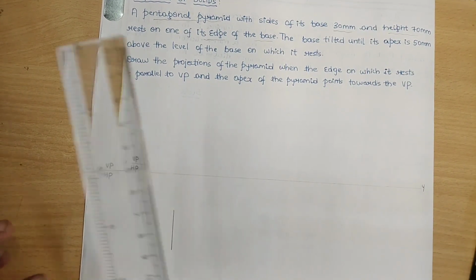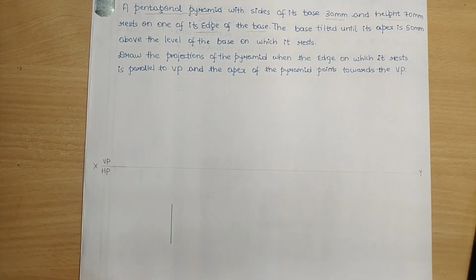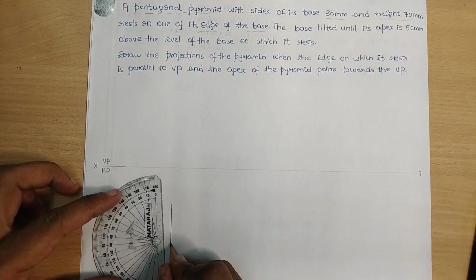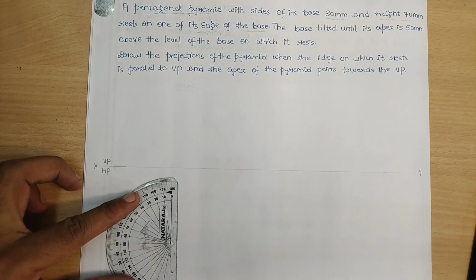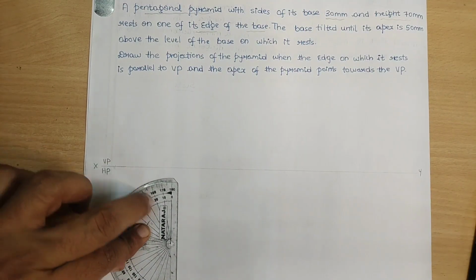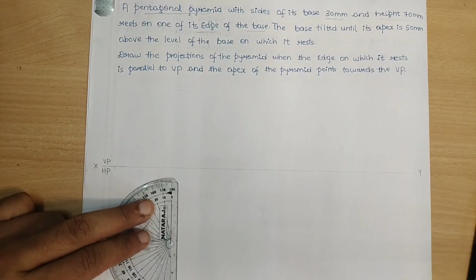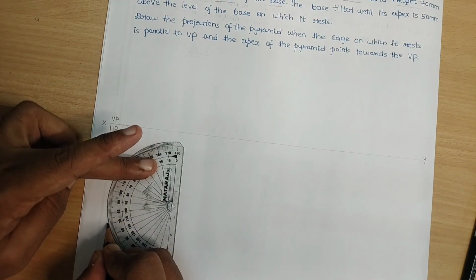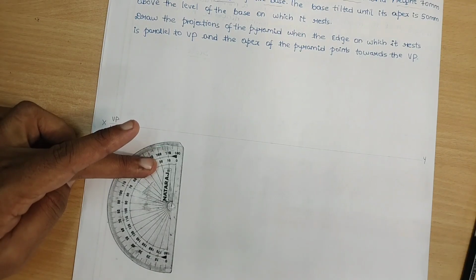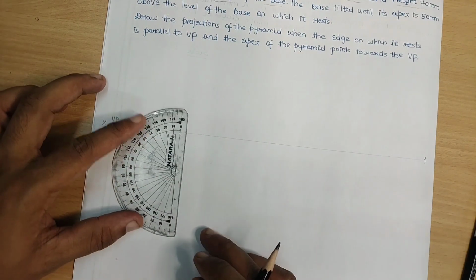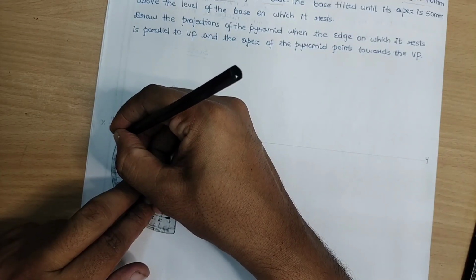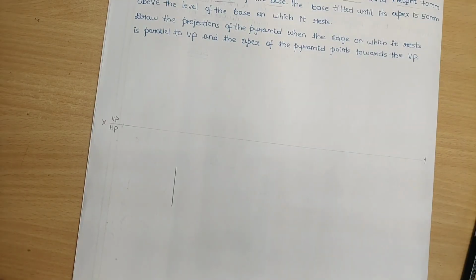The exterior angle is equal to 72 degrees. I will make use of a protractor here. I will keep it at this point and measure 72 degrees on either side. The interior angle is 108 degrees. I have marked 72 degrees here, followed by one more 72 on the other side. 72 degrees is now completed.